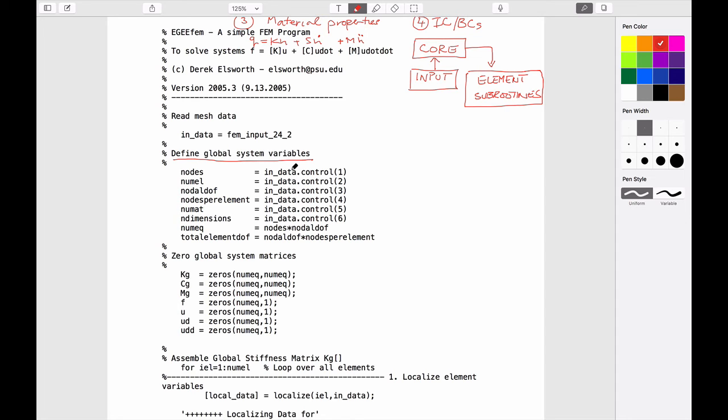You can calculate how many storage spaces you need for the coordinate data, for the material properties, and for the indexes moving between the global elements and the local elements, etc. Instead of making a whole bunch of arrays whose size you change depending on how big the problem is, because you don't want to use any more core computation time than necessary, you just dimension this one big array, and it automatically divides it up into the right parts.